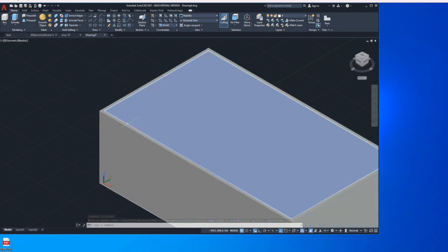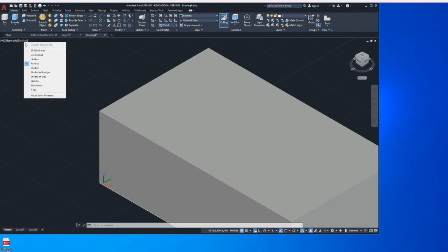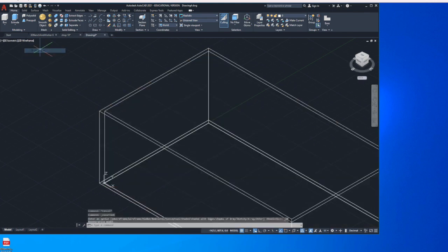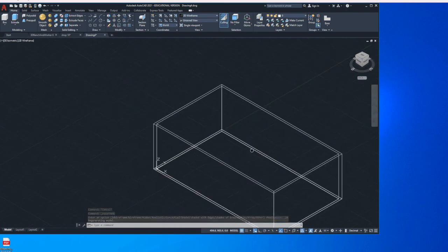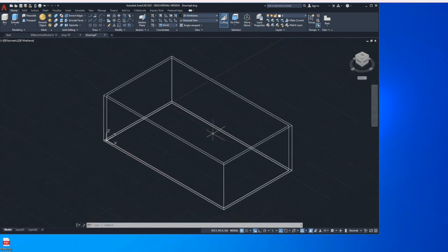So I want to change that so I actually don't have the center of the building filled in, because I want to put my work equipment and my workers there. So what I can do is use a subtract command and subtract this inner box from the outer box. It'll be a little easier to do if I switch from the realistic view back to the wireframe view so I can see the boundaries of my surfaces. And I will now type subtract.